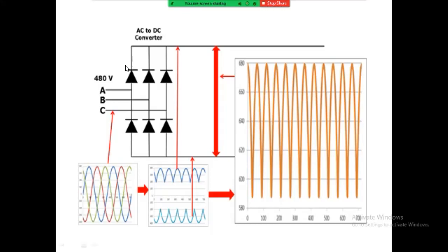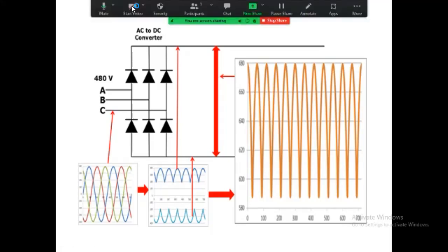So this is the graph which is shown, means the ratio or the voltage level which can vary between 440 volts to 680 volts. Generally we show one voltage range, means we can change the level of the voltage by adjusting the frequency to maintain our V by F ratio constant. As per this, we are taking a voltage range of 540 volts to 680 volts, and hence this graph will be shown accordingly. Okay, so this is all about the working principle of the variable frequency drive used in electrical systems. Thank you.